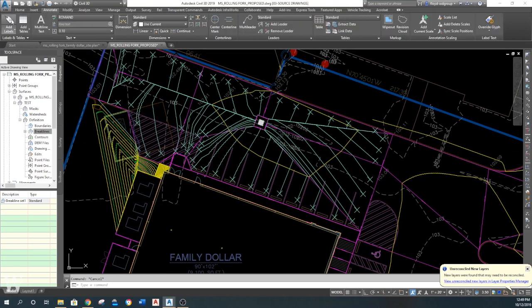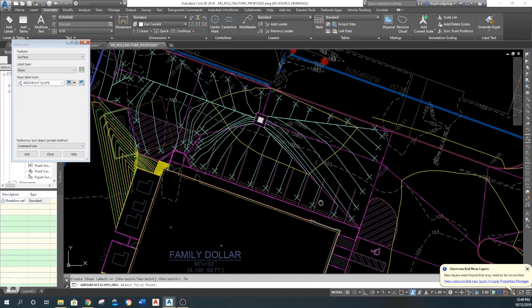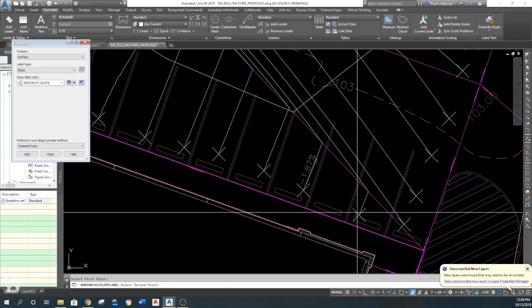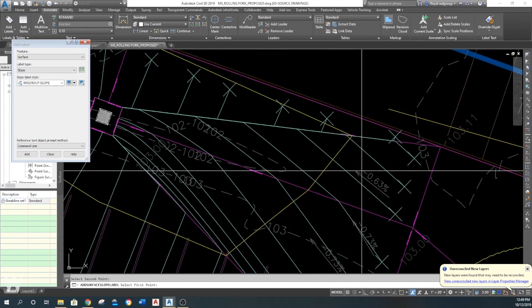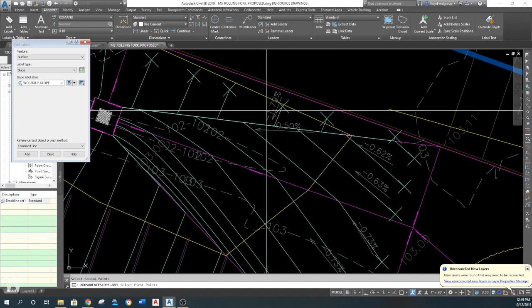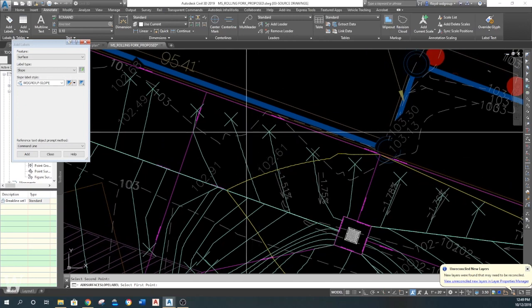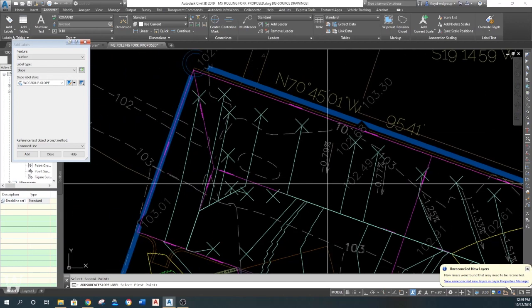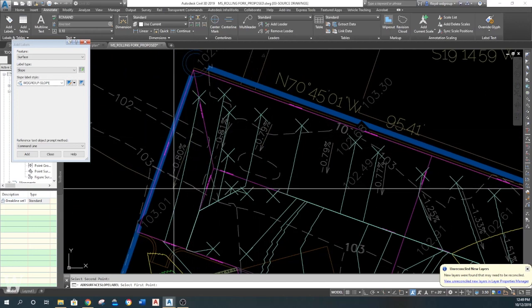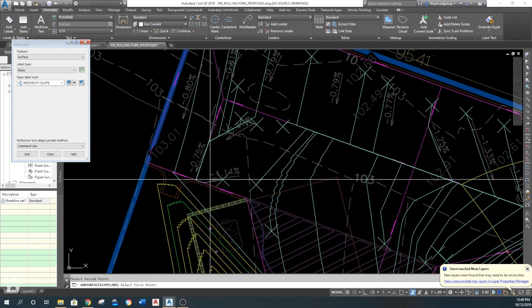So now let's go to annotate, add line, add surface, hit slope. I've got my own slope thing. Pick a surface, 2 point. I'm just going to start putting them along here and make sure that they look good. 73, 73, 73, 63. That's that way. Everything looks pretty good. There's nothing particular about them. They don't have to be any great. I'm not trying to be perfect with placing these, and I won't be when I put them in my drawing either. What I'm doing right now is checking slopes. I got a little bit of a flat spot right there.